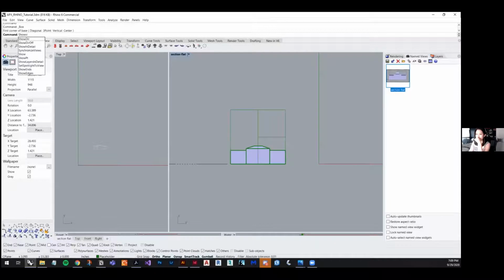But had I made a named view and saved it, I could just go back to my named view, remake 2D the additional few elements, take those few elements back into Illustrator, and I could just add them on top of where my drawing is using Control F, which is Paste in Place, exactly in the spot where it is in the image, if that makes sense.